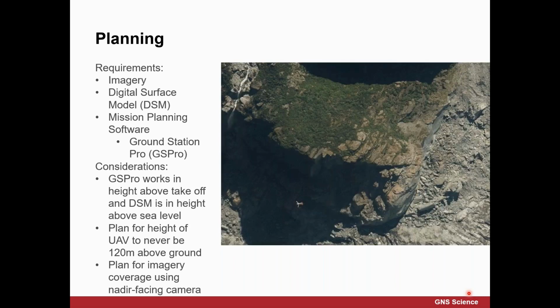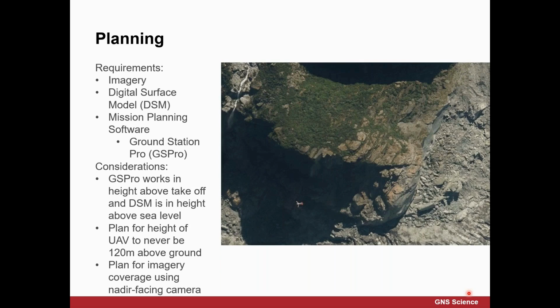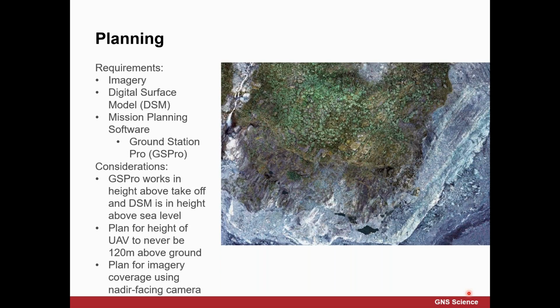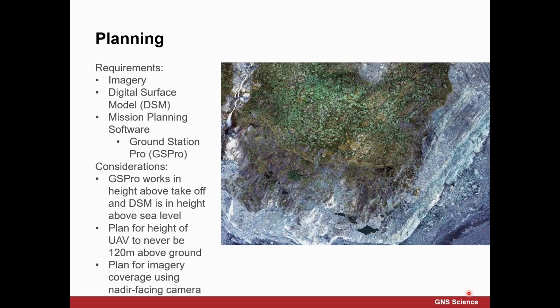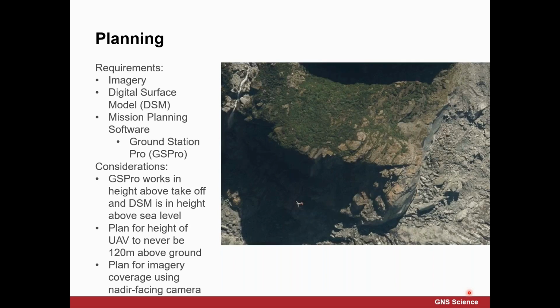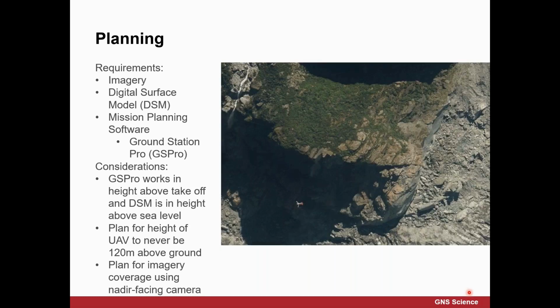And this is just a GIF showing what we're planning off and what we get afterwards. It's an orthomosaic created by our camera on the drone. So there's a lot of shadow zones. The imagery isn't always super accurate, and sometimes the DSM on the slopes is not either.